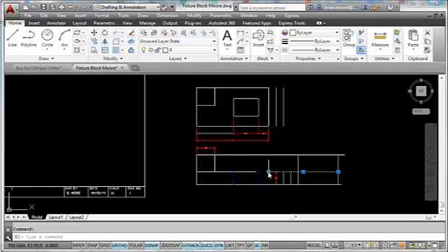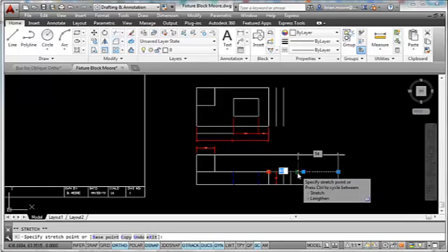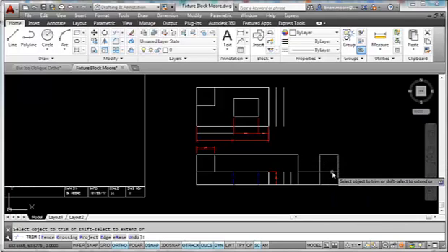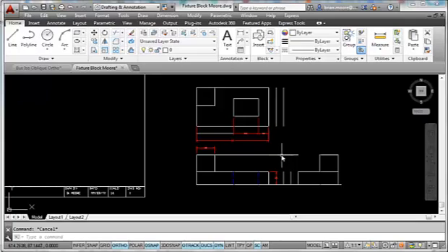And then I can trim that one up. And I want to trim these, well, I won't trim just yet. I know that this top piece is 25 wide, so I can offset by 25. Offset 25. Frame it in. And then trim. Trim out this piece, this piece. I don't want this piece in here, and I don't want that. And then I can get rid of things that I don't need anymore.